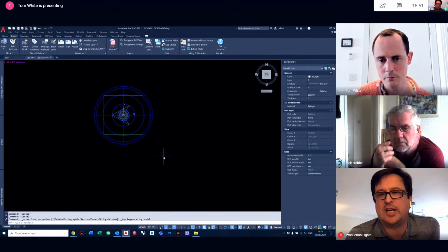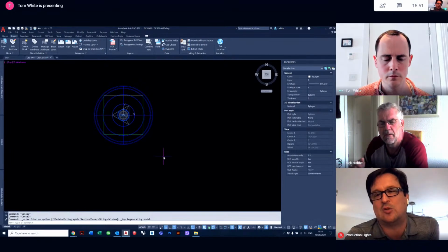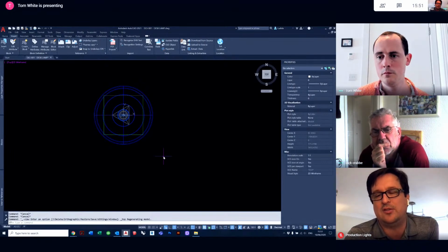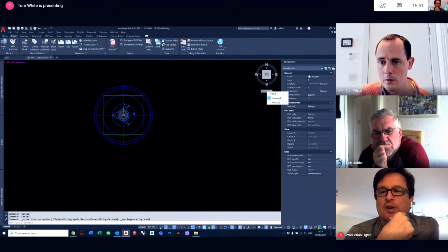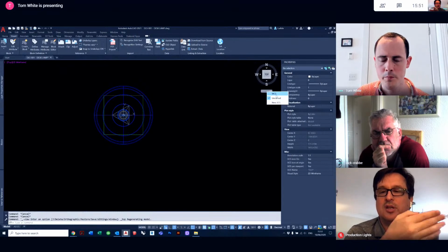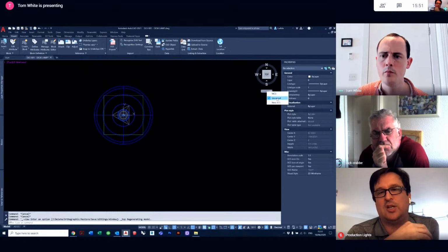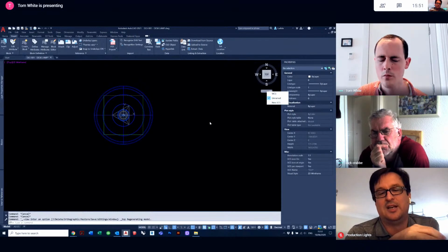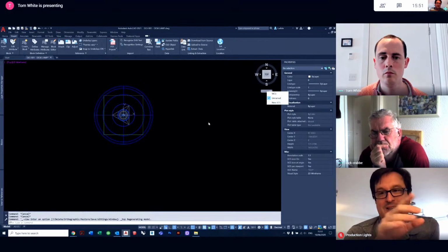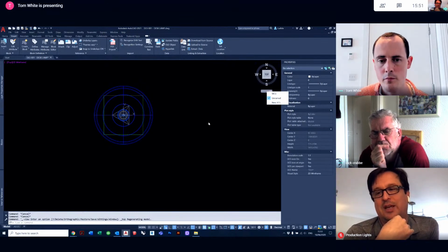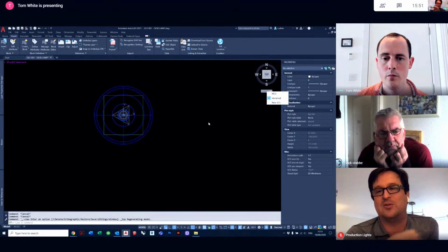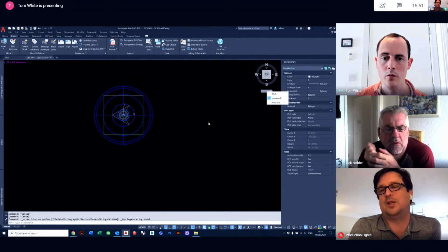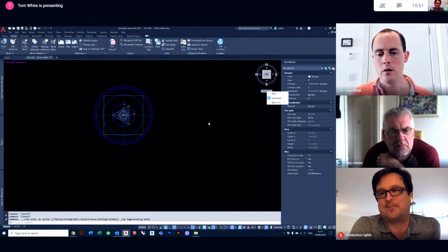The other thing, just very quickly checking, under the compass, under the wheel in the top right corner, if you click on the little grey bar below, I believe it will come up with what UCSs are available to the drawing. So you can click either World UCS or a named UCS. I would say to anyone who is putting a different UCS in to use the UCS command and save it as Tom's whatever, just so people know there is a different UCS in there and whose it belongs to. Then if you pick up the drawing separately, doing your own work, you can click back into World UCS and off you go again. And it saves the user one separately.